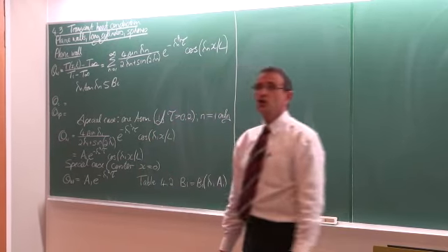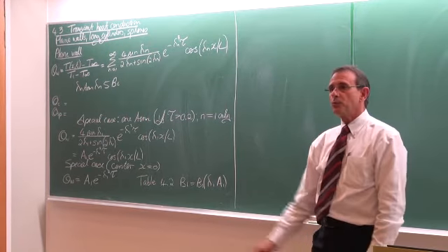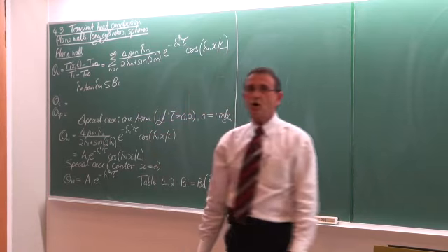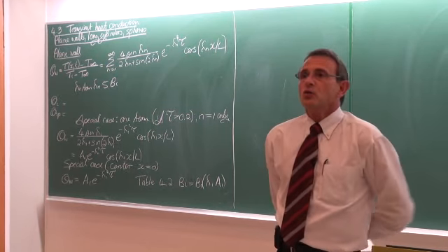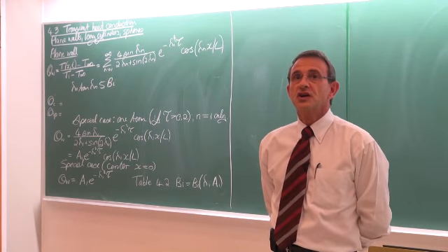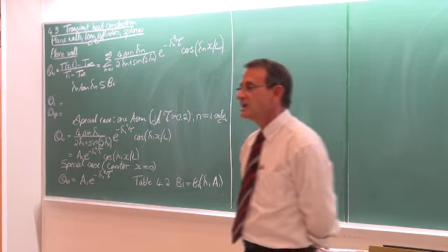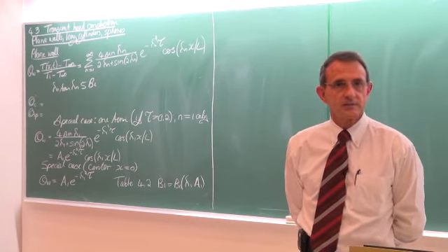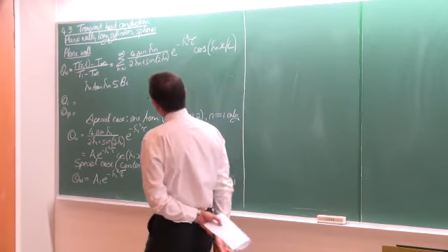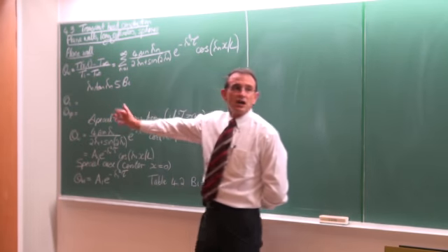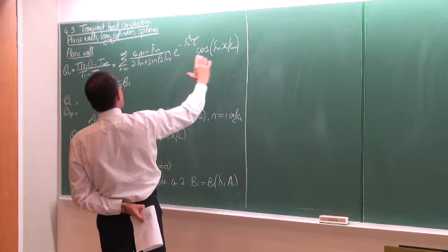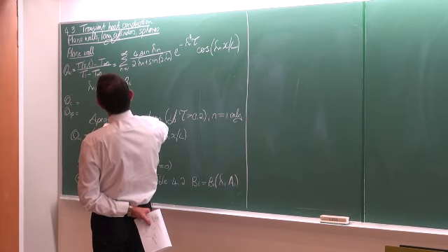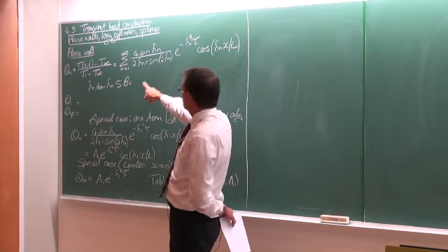From the one-dimensional heat conduction equation, we ended up with a partial differential equation that could be solved by using the method of separation of variables. But before we did that, we created non-dimensionalized groups so that we can change the 8 independent variables to, let's call it, 3 independent variables. And the result of that was that this equation could be solved in a non-dimensionalized format. So this is the non-dimensionalized temperature. Non-dimensionalized temperature is equal to the sum of an infinite series.